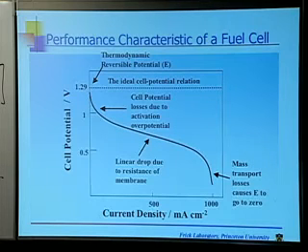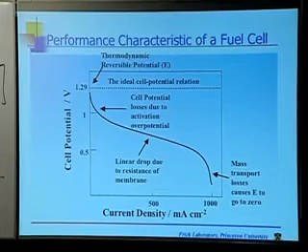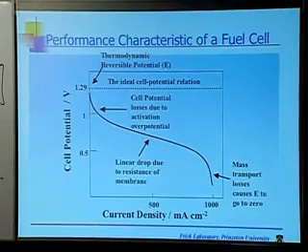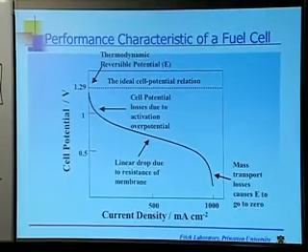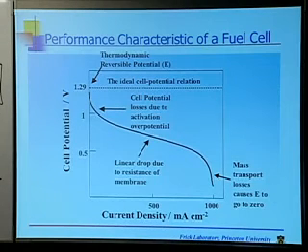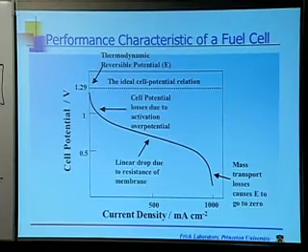We're operating at that temperature because under those conditions, we have favorable rates of reaction at the two electrodes, and we have a favorable rate, more importantly, for proton transport across the membrane. That is, there is an activation barrier to get the protons across the Nafion, and 60 to 80 degrees takes care of it. You'd like to go hotter, but above 80 degrees, even when you're humidifying the cell, it's really hard to keep water in the Nafion. So 80 degrees becomes sort of a pragmatic cutoff on the high temperature side. 60 degrees you need to get the resistance of the Nafion down to where there's not too much of a loss. So what do we see?